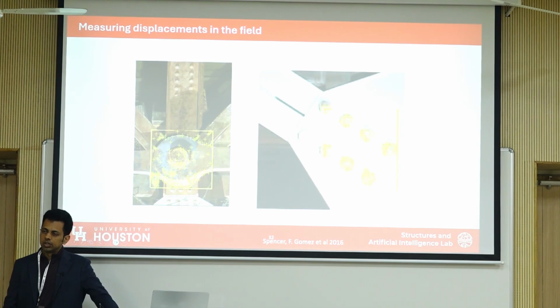One is you can use some computer vision technique to make measurements and then use the measurements to categorize the severity. For example, you have a scale for what different sizes of cracks mean. Then you can use that scale after you measure the crack size to classify the severity.